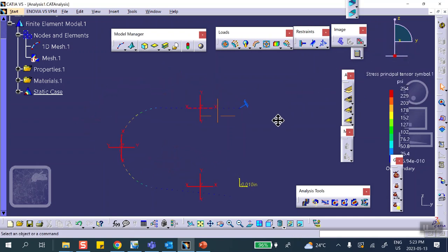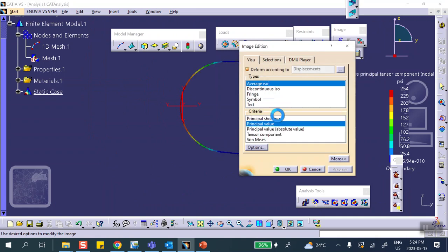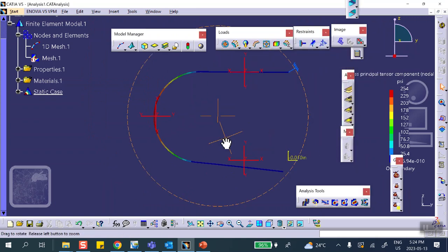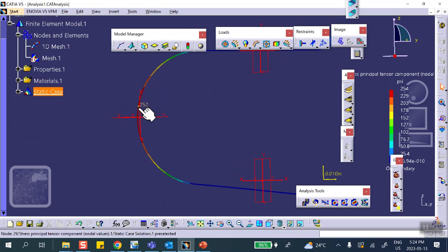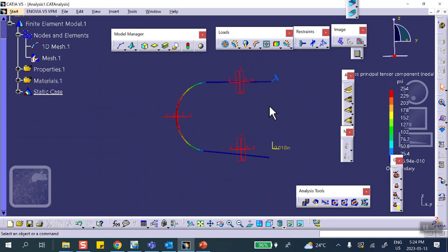Now, unfortunately, we cannot see the stresses. The only thing that we can see, if you look at this, where you have the displacement, there is stress, principal stress, but unfortunately, the only principal stress that it shows us is the axial one, which is kind of useless. And of course, you can change the color here if that's important to you. Now, needless to say, yes, we know that over here there is axial stress, and that's why it's red there. Because remember, you're pulling this thing down. That piece goes through axial stretching. See that? Good.